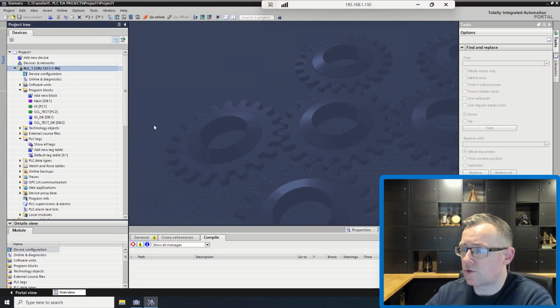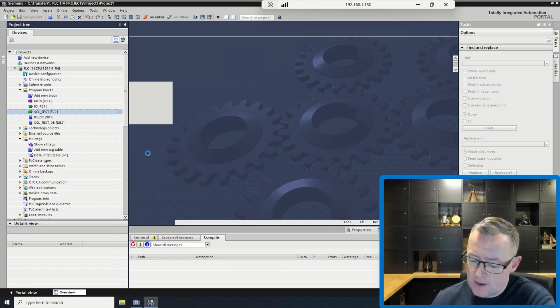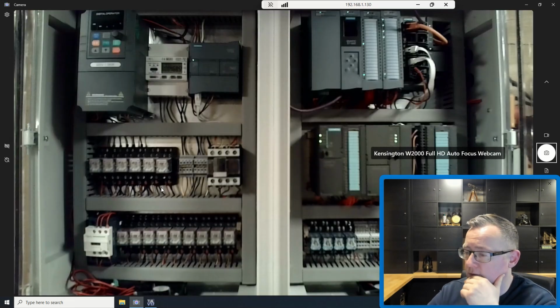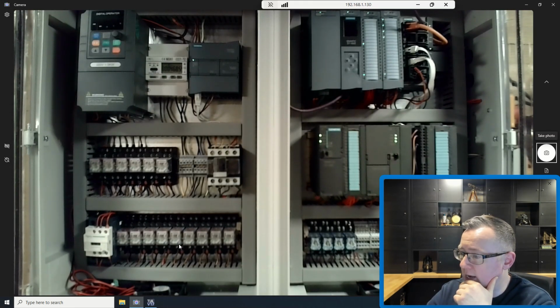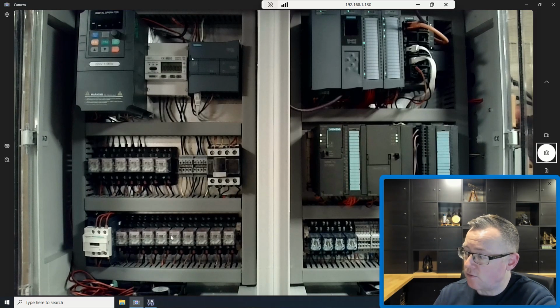In this video, I'm going to run through what's called a case statement or a switch statement. I'm going to continue on with structured text and build a program where a value changes. An integer can change from 1, 2, 3, 4. Essentially, I'm going to take some relays here and turn some of them on and off based upon a value being given 1, 2, 3, or 4.